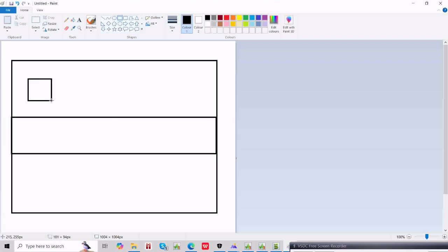So let us say I have an equipment here and I have another equipment here, and I need to start my routing. So how are you going to route? You're going to come here and run on the pipe rack. This is what the pipe rack we created is for. This is a systematic way of routing on a pipe rack with proper supporting. You can give support here, you can give support here. This is the way of routing a line on the pipe rack.